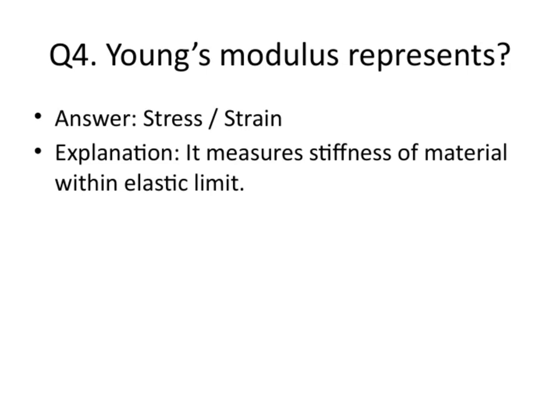Let's take a closer look at what Young's modulus represents. The answer here is stress divided by strain. Essentially, it measures how stiff a material is within its elastic limit. When a material is deformed under a load, stress is the force applied per unit area, and strain is the relative deformation or extension. Young's modulus tells us how much stress is needed to produce a certain amount of strain, giving us a clear picture of the material's stiffness.